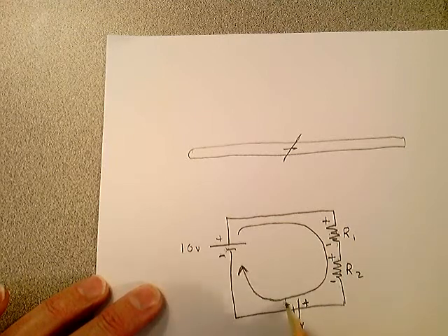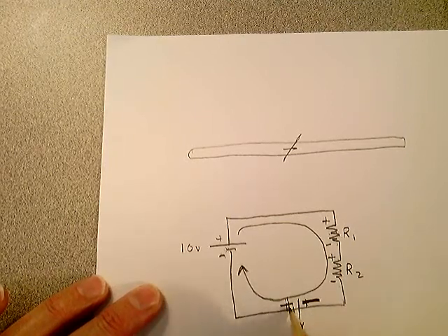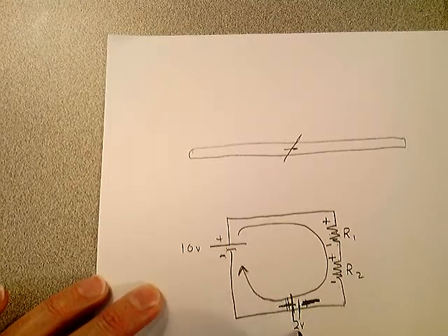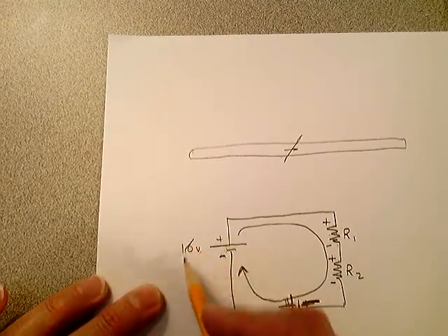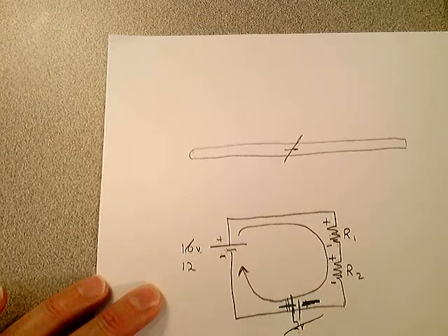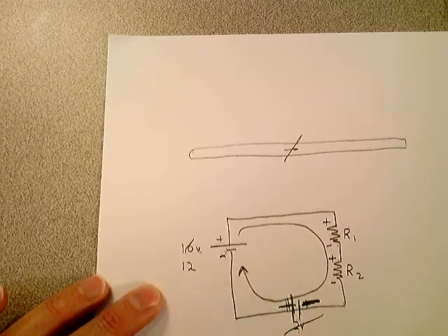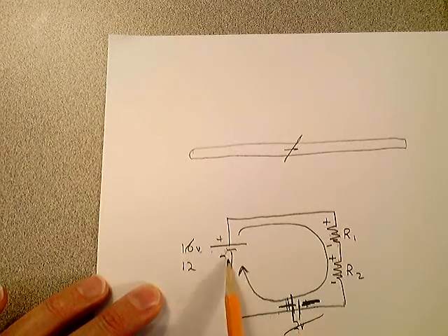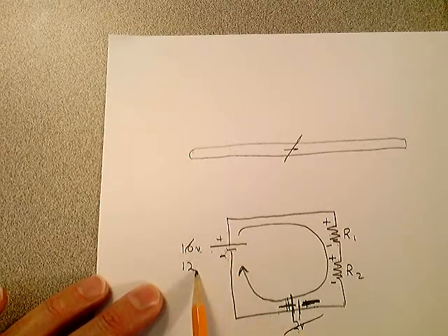Turn this around, make this the plus side and make this the negative side. Make that plus and make this minus over here. There's a plus and there's the minus. You could replace this with simply 12 volts and get rid of this, because they'll be aiding one another. You have 10 volts here and 2 volts here. If it has the same polarity, minus to plus, you could just replace this with 12 volts.